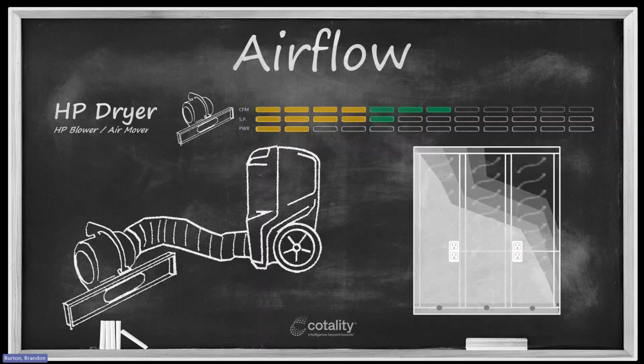If the water migrated across the floor at a depth no greater than the carpet and cushion, which is lower than the height of a wall plate, and then simply wicked up the drywall, then my first attempt is going to be drying it from the inside surface, right? If that's not effective, then I will get more effective or more aggressive with my means for affecting drying.